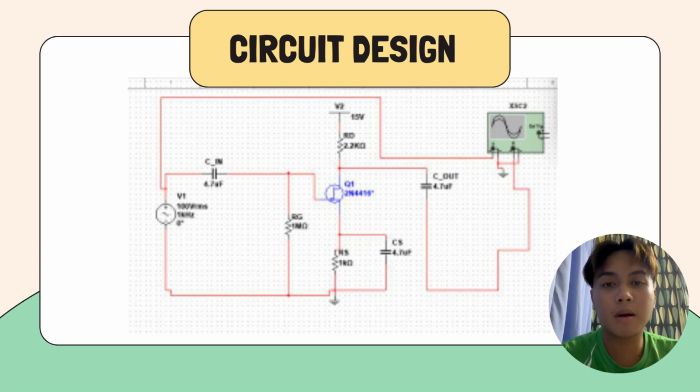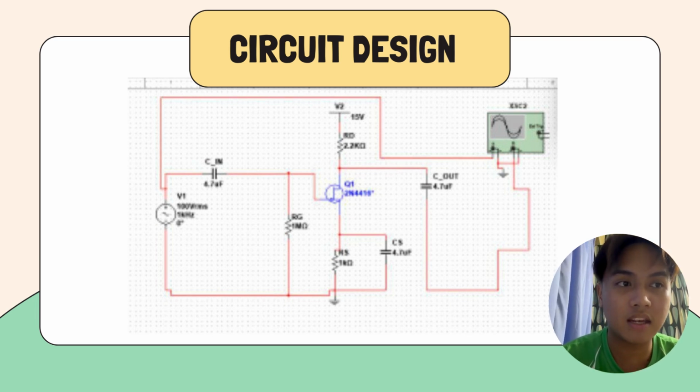I will be explaining the circuit design and the specific components that we use to meet the assignment requirements. For this design, we use the 2N4416 JFET, following the assignment guidelines. I have ensured the model parameters are set to an IDSS of 10 mA and a pinch-off voltage VP of 4V. These values are essential for calculating our Q point later on.